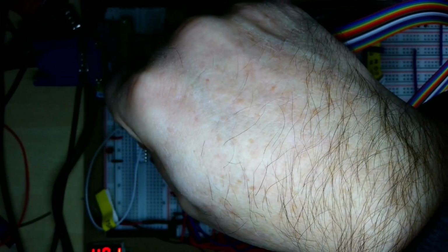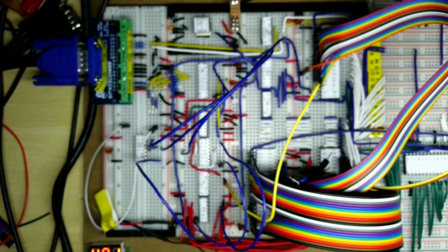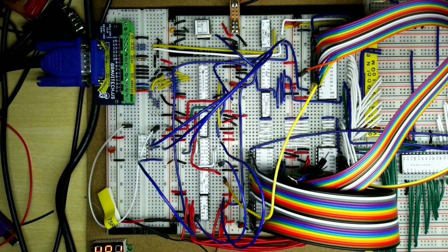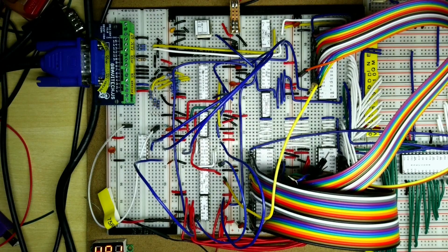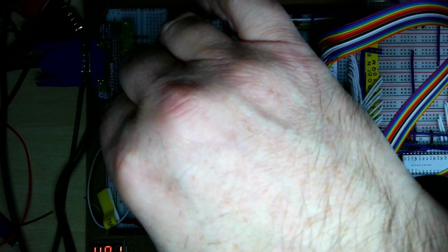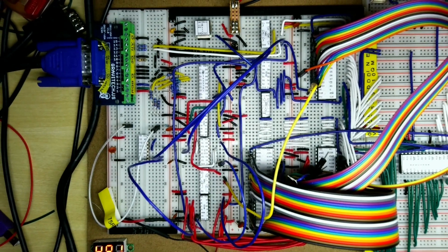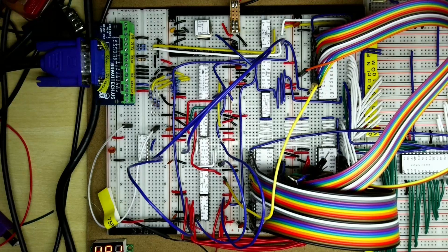So if I just plug that into there, so I've got the display on the LCD monitor to my left here. I'll take some photos of the changes here. So if I just put this to 1 delay, 4Q, which is 1 clock delay, and there is still a little bit of a gap. If I now put it to 3Q here, so that's 2 clock delays, and that looks pretty good. I can't see any difference. I think that's about the setting we need.